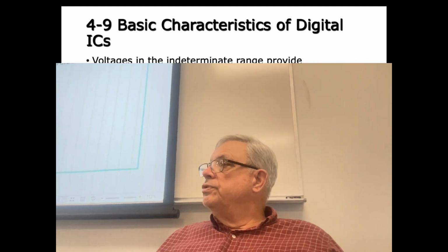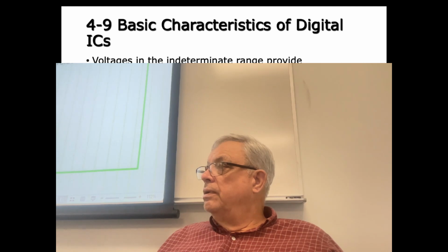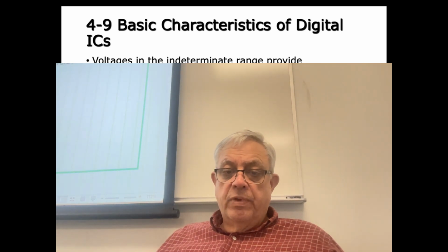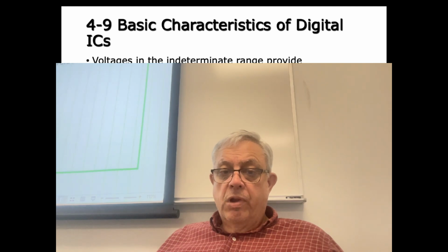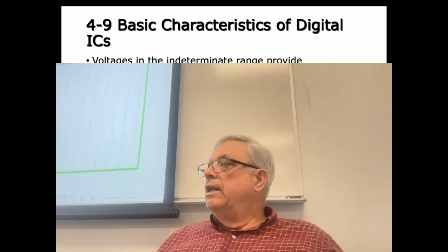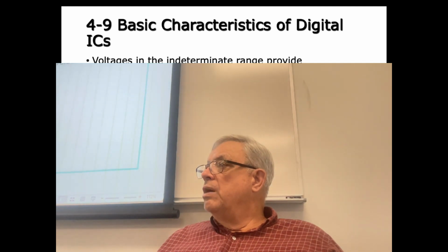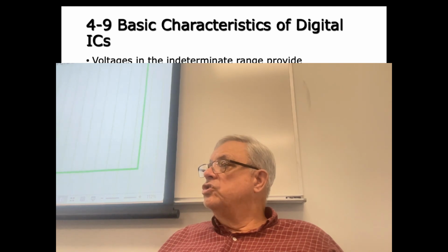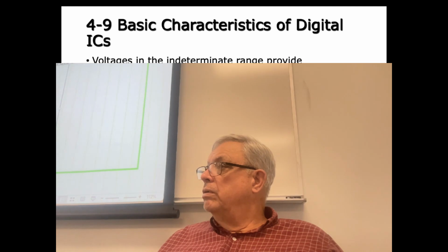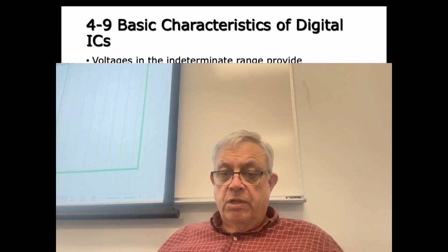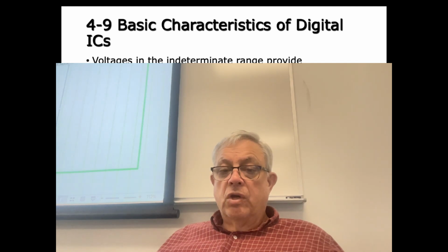We have talked about this as recently as last class period. A 1 is a 1, a 0 is a 0, except that a 0 can be up to 0.8 volts. And the 1 can be as low as 2 volts. I can't do any analog to digital conversion based on logic outputs. I have to have a stable external source providing the value that I want to encode. But that also says, as long as it's not in this intermediate indeterminate zone, I know if it's a 1 or a 0.